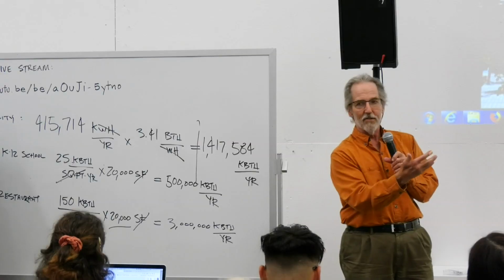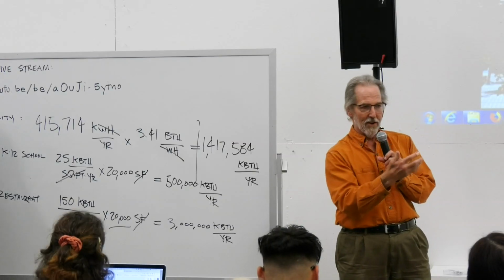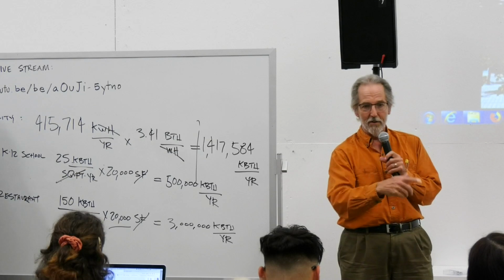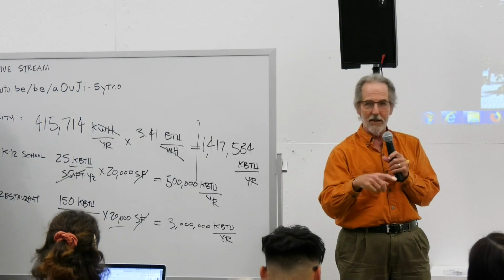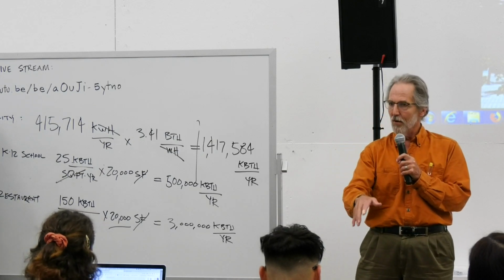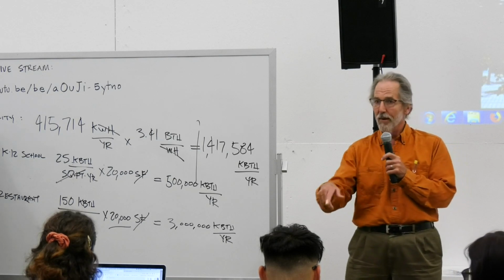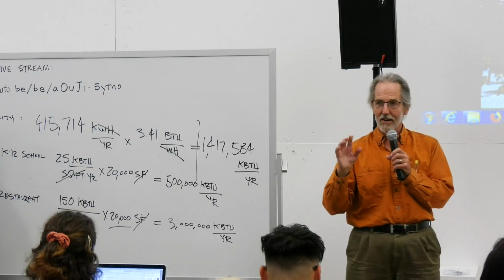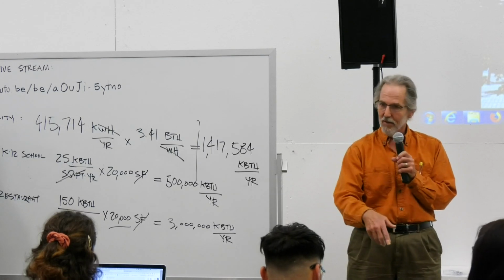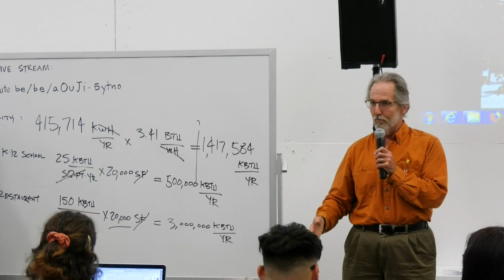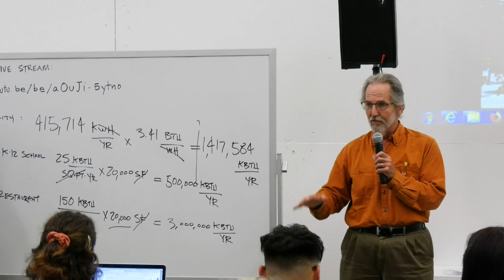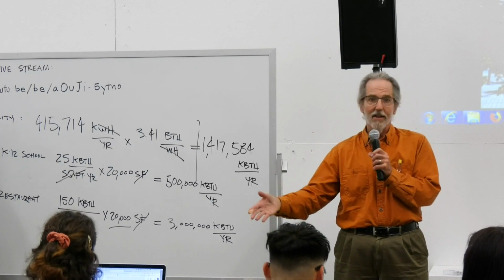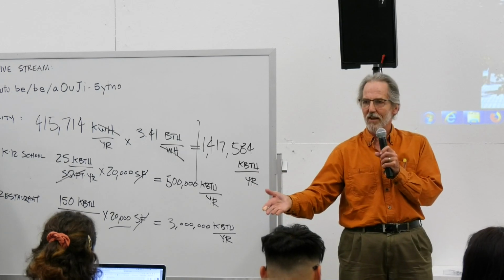You need to know, if I'm going to use this panel, here's how efficient it is. I'm going to be in this zip code, so I know enough to go into PV Watts and say, I'm using this panel in this location. My roof area is this much. I know what I can generate on site.